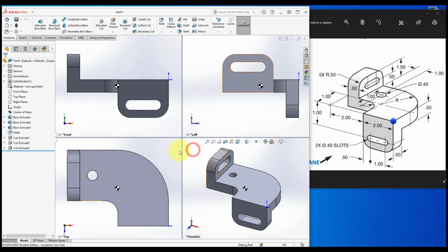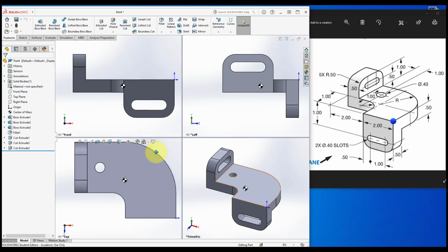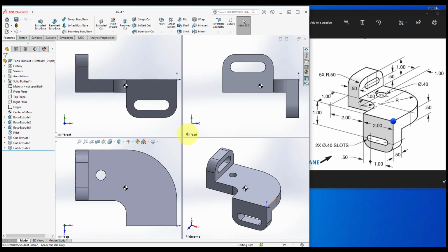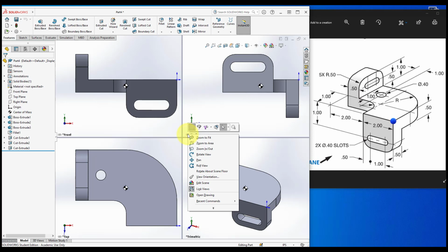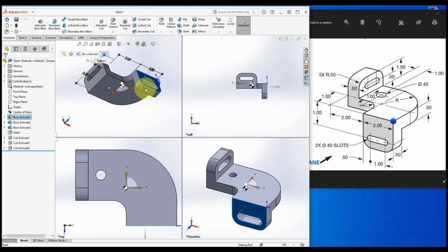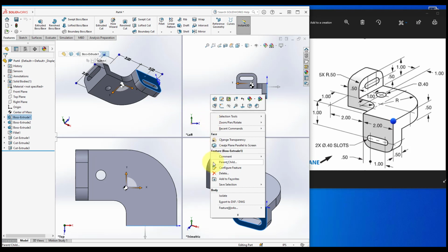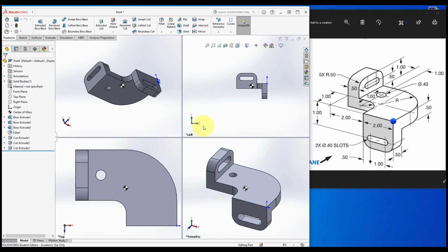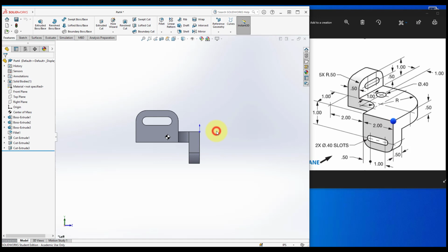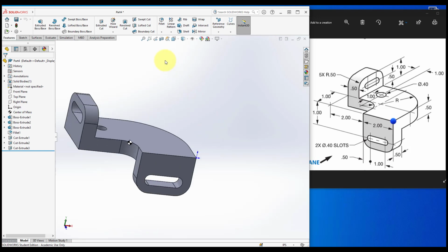And then finally, to get back to it, you can just click in any of these windows. You'll see as you click into these particular windows, they become active. And then you can rotate or move the parts. And the thing is that they're linked. You'll see that the trimetric view isn't linked. And you can right-click and unlink the views. So now the views are not linked, so I can zoom out on this one and I can rotate this view. And then I could right click here again, and can I forget. I don't think you can go back and relink the views once you've broken the links. But I can go back into any of these, go under my view orientation, and set the number of views back to 1. All right, so that's this part.